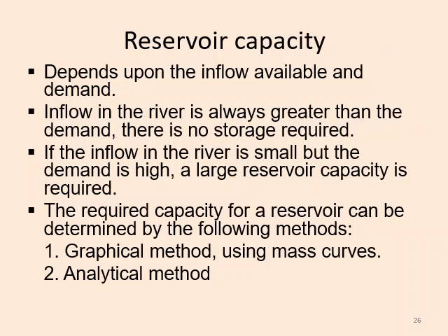Now, reservoir capacity. The storage capacity will depend upon the inflow available from the river or stream and the demand of the particular area or city where we are going to supply the water from that reservoir. If the inflow in the river is always greater than the demand, then there is no storage required.